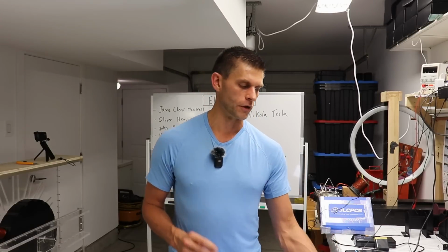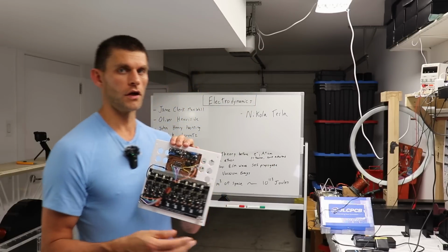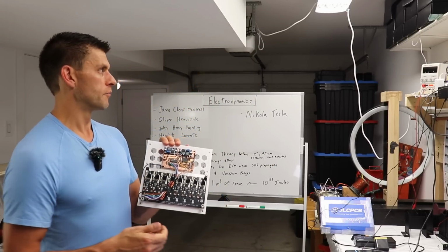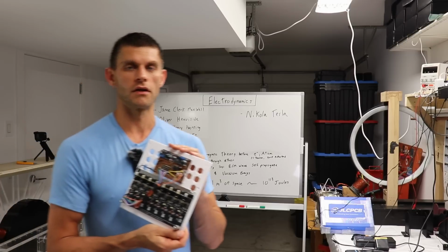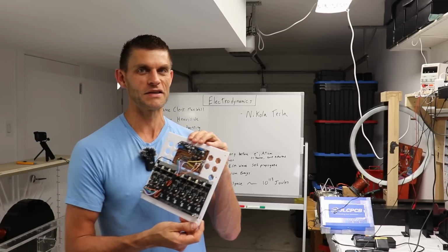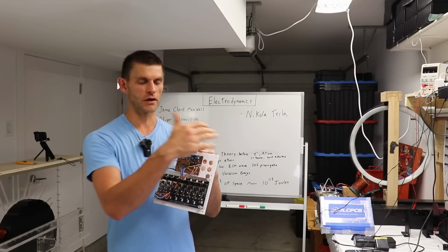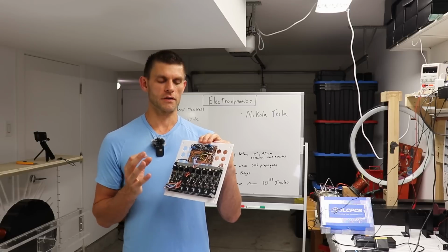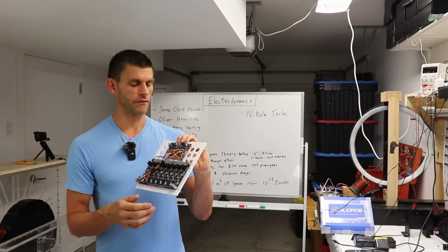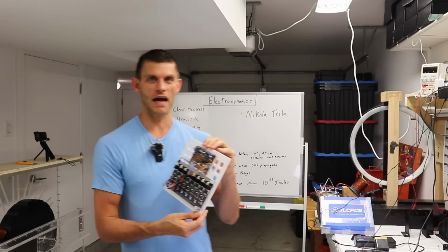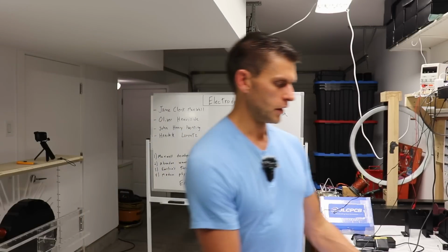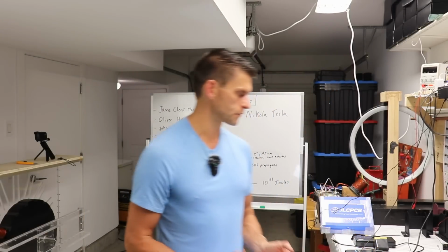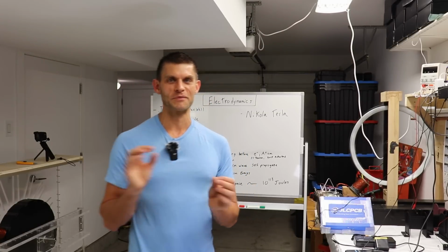We're going to fire up this first board using not the batteries, which we are buying, but a DC power supply, just so it's got some circuit protection and over amperage protection, in case something goes wrong. We are going to enclose these boards. There is a danger of MOSFETs blowing up and things like that, especially the very first try. So it is going to be a bit of a trial and error kind of thing. But overall, we're getting very close to firing this machine up.